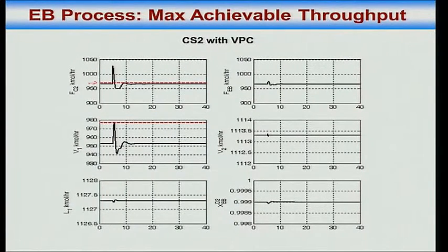That transient can never exceed 977 or whatever is the limit on that, whatever is the red limit. So I am operating at about 20-25 kilomoles lower boil up in the first column. That corresponds to a 5 kilomole per hour loss in throughput. So now the process is stable, but instead of getting 970, I get 965.